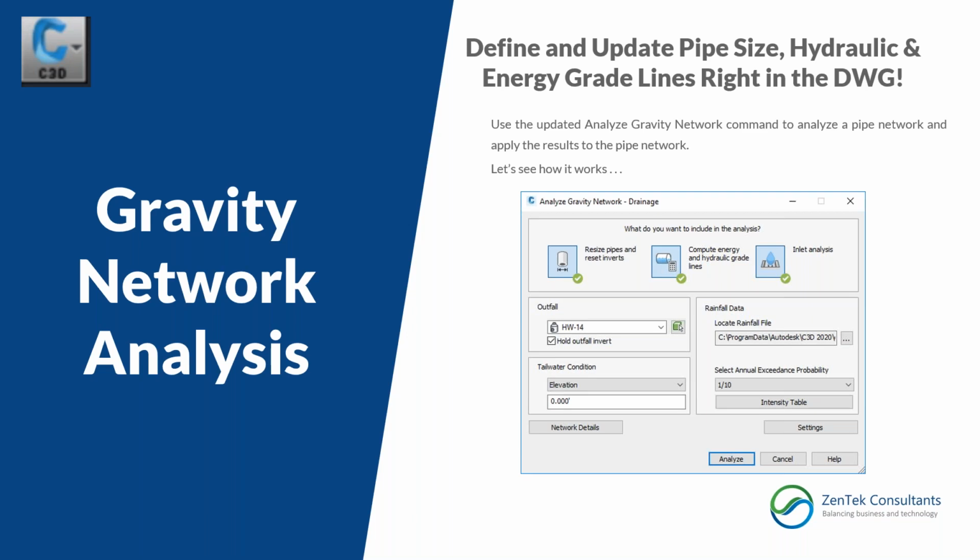We can also compute energy and hydraulic grade lines, and we can even do basic inlet analysis in terms of depth and retention, and when things are in surcharge. Okay, so there's a lot of functionality that we can now handle directly inside Civil 3D rather than having to export to a third-party system. So let's go ahead and jump back over to our Civil 3D here.